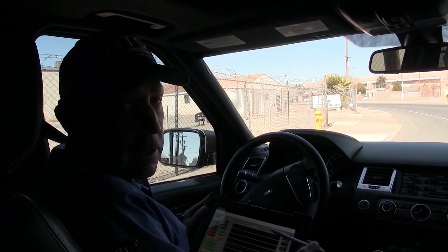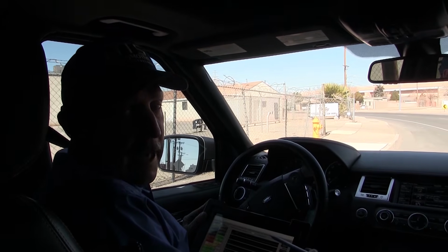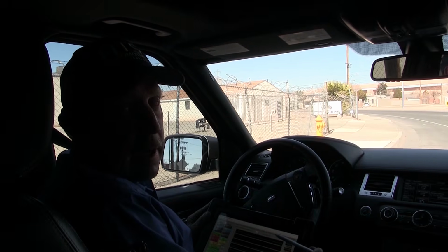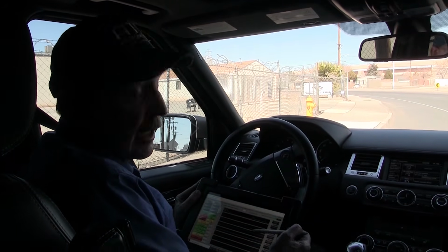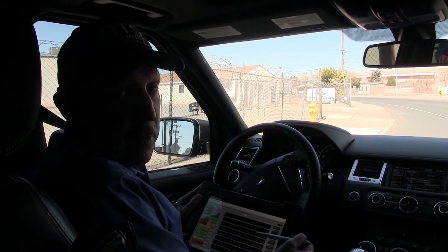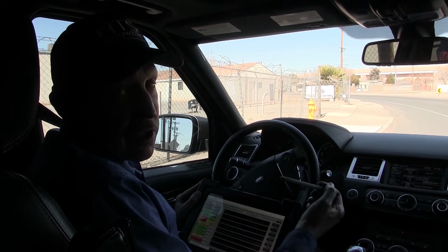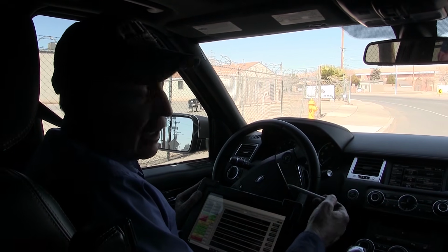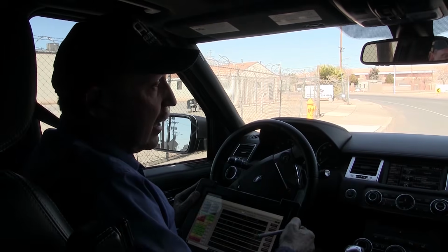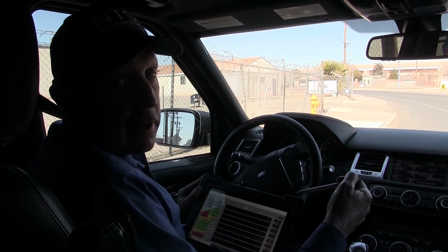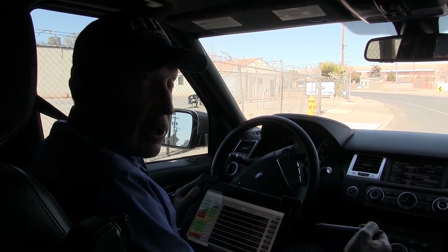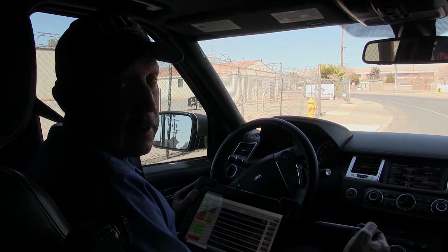So what I want to do now is put a 5-gas analyzer on this car, get a tailpipe reading and match it against these readings here, and see if we really need that trim. Maybe we have some type of a feedback problem, and that's why it runs bad. So let me get that gas analyzer connected to the car, and then let's check it to make sure that the correction is for real.